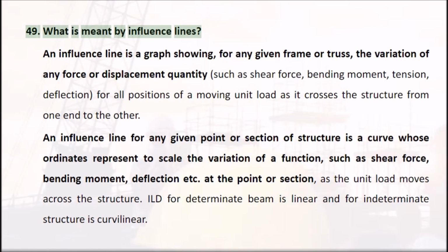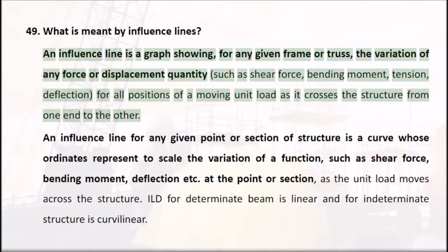What is meant by influence lines? An influence line is a graph showing, for any given frame or truss, the variation of any force or displacement quantity, such as shear force, bending moment, tension, deflection, for all positions of a moving unit load as it crosses the structure from one end to the other.